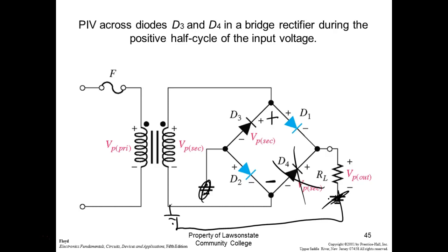And you look, it's got two leads in the center marked AC, and the outside one lead is marked negative, the other one's marked positive. Is this a negative or a positive? It depends on which one you make common, right? So the common is established on the load side. Instead of the transformer establishing the common, your load establishes the common. And all we have to do is change the common on our load, and we could have either one of them. Y'all want to see that?